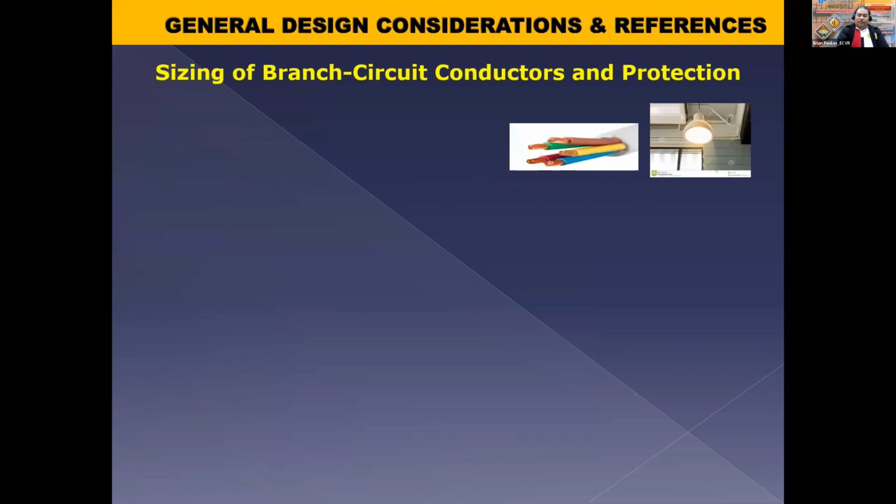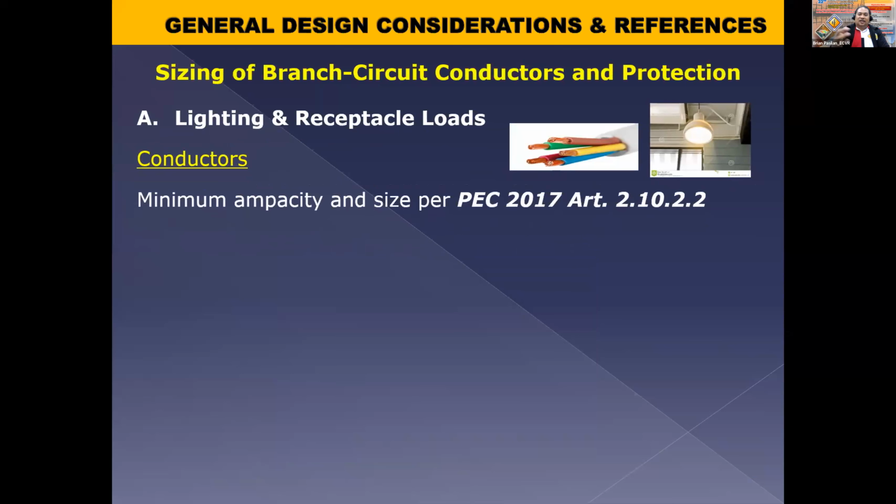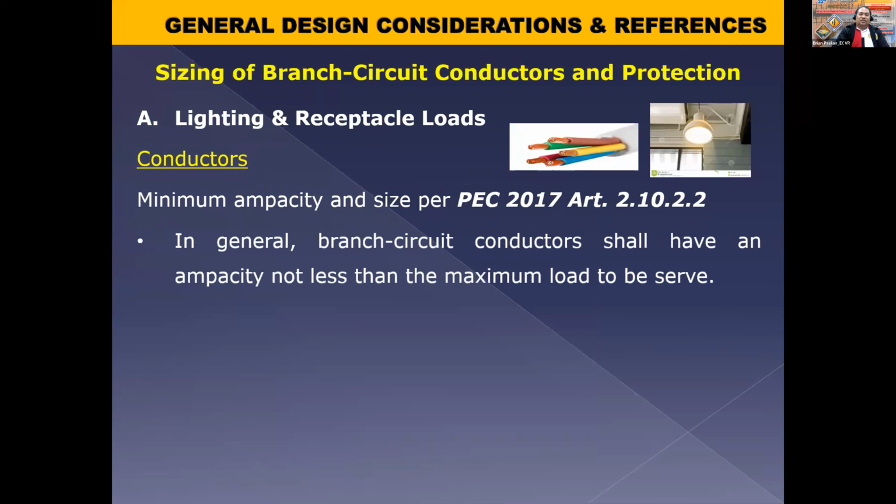Okay, so for sizing of the conductors, what we had earlier were the demand assumptions. This is now the actual sizing for conductors and circuit protection, as per PEC 2017 article 2.10.2.2. Please look into this also so you get used to opening the PEC. This is our exercise.